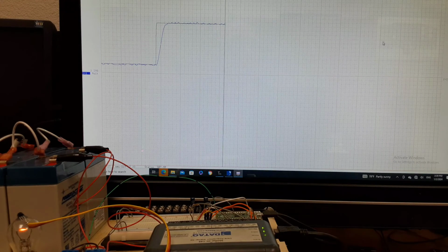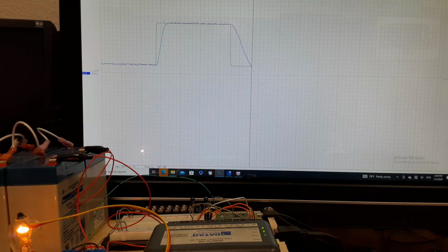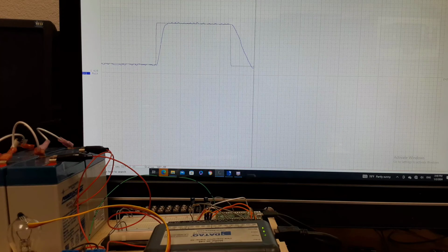Now you'll notice when I set the temperature back to 50, the slope of the cooldown is going to be less steep than the heat up slope. And the reason, of course, is because I can't control the cooldown. I could actually, if I put a little water on the sensor, you'll notice it'll drop the temperature quicker. But I don't have an air conditioner or anything on that sensor, so I can't really control its cooldown rate. Also, we'll see how it does latching on to that lower set point.